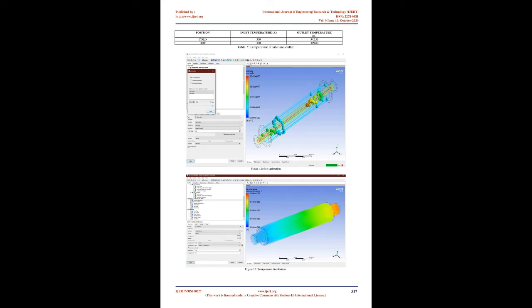Boundary conditions are used according to the need of the model. The inlet and outlet conditions are defined as mass flow inlet and pressure outlet, as this is a counterflow and parallel flow with two tubes, so there are two inlets and two outlets. The walls are separately specified with respective boundary conditions. No slip condition is considered for each wall. Except the tube walls, each wall is set to zero heat flux condition. The details about all boundary conditions can be seen in Table 3 as given below.